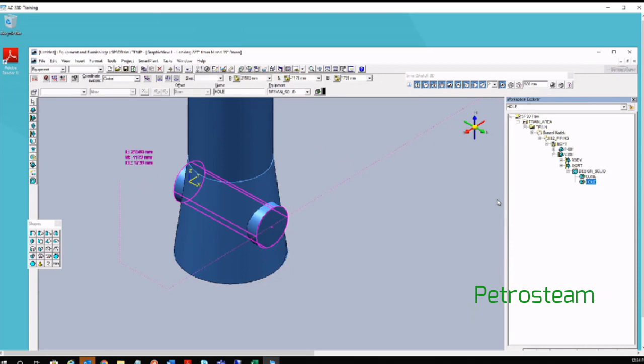To make it negative, for getting the through hole, once you select the shape, you can see here it's under design solid. This is the design solid you have placed using this. So the shape should be within the design solid. Then after this equipment name, there is a drop down available over here.